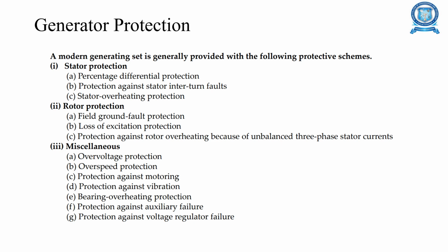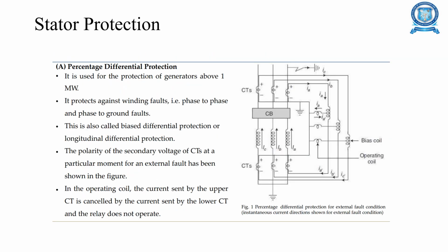In rotor protection: field ground fault protection, loss of excitation protection, and protection against rotor overheating. And in miscellaneous: overvoltage protection, overspeed protection, protection against motoring, protection against vibration, bearing overheat protection, protection against auxiliary failure, and protection against voltage regulator failure.